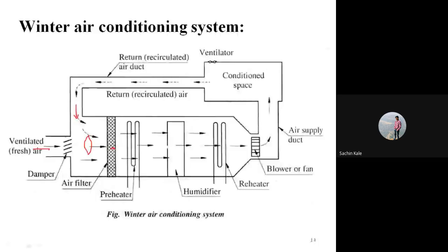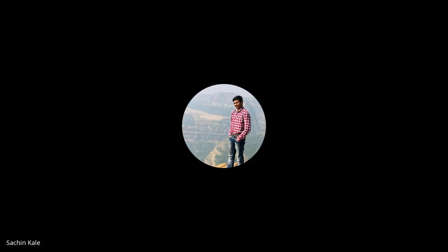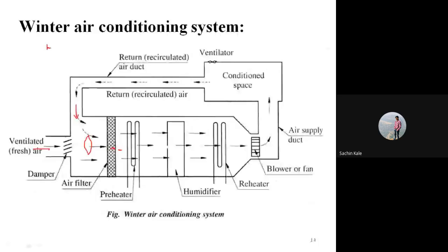Now, as in case of winter air conditioning system, the desirable process which we require to do is nothing but heating and humidification. So here, that mixed air will be passed over the preheater.